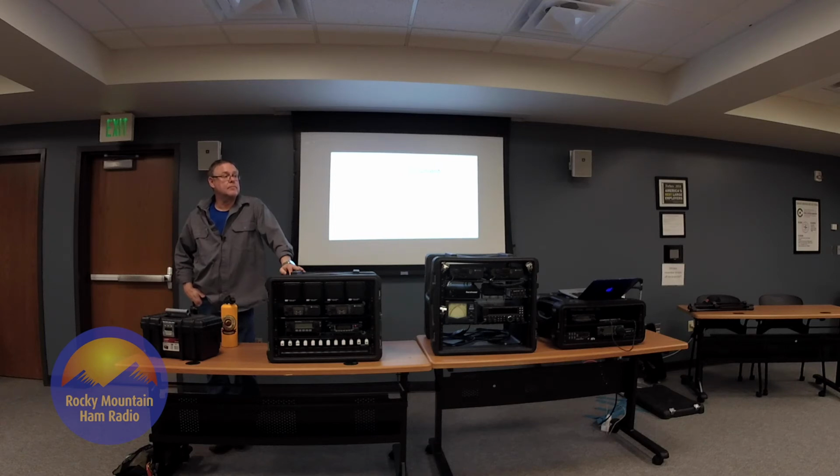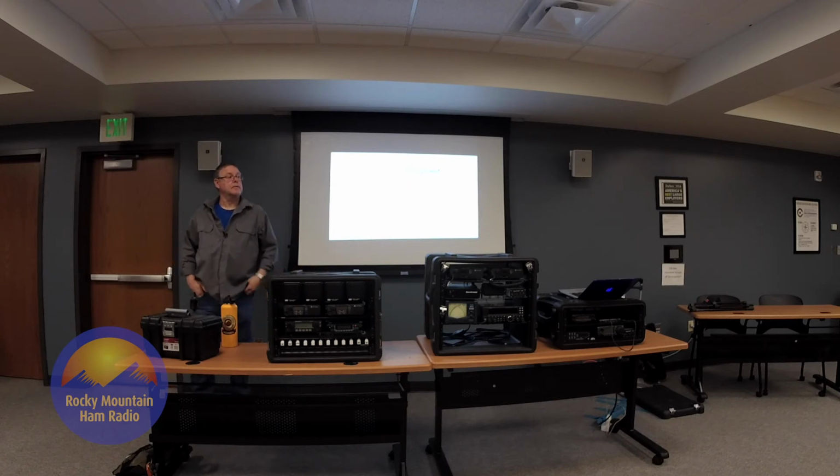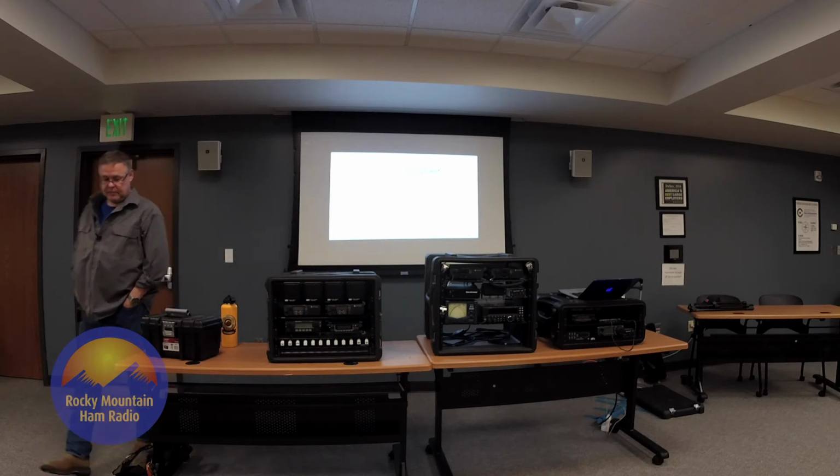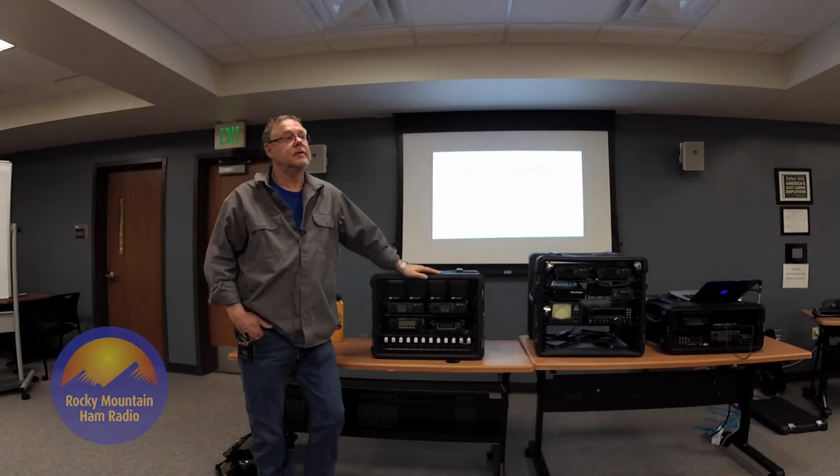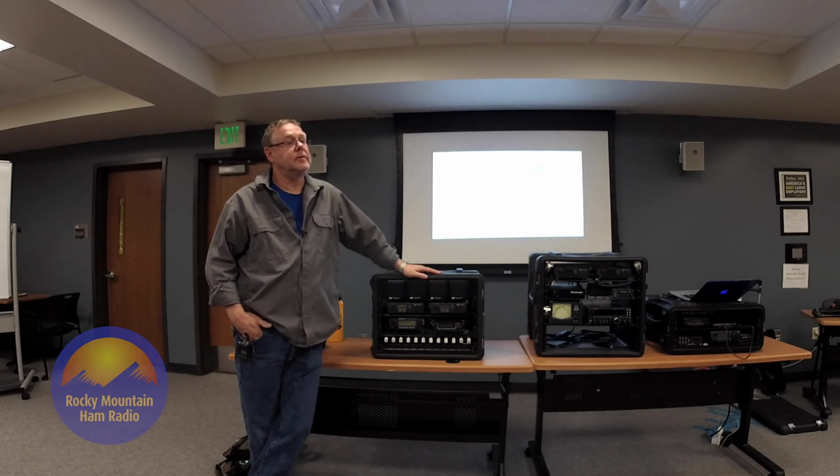That's good for HF. If you're trying to do something for, say, MARS, and you want something really wide-banded, you're looking at a resistive terminated folded dipole. It's called a T2FD. That is pretty much wideband from 1.8 to 30, and it doesn't need a tuner. You can hang it up in a tree or stretch it between a couple of buildings. You're looking at a couple of $100 for the antenna, but then that solves a whole lot of issues that you have with tuning. But it's not a very high gain antenna, but in most cases, when you're trying to do that, you don't really need it.